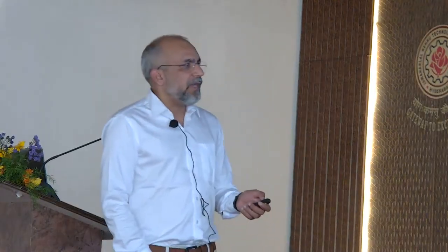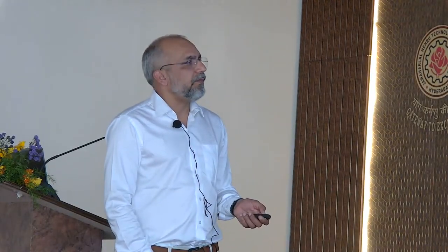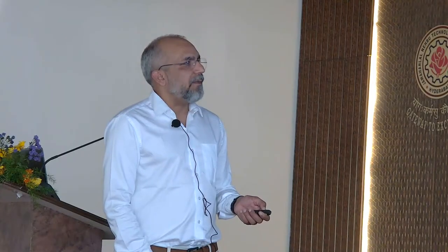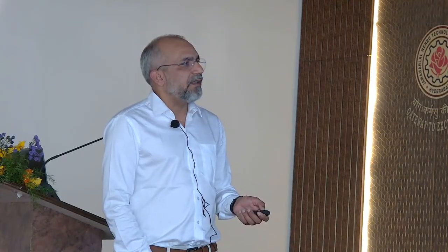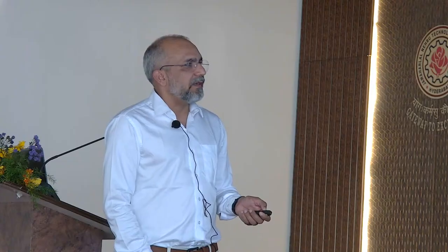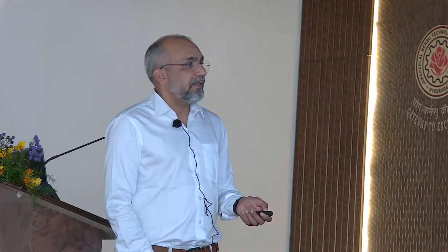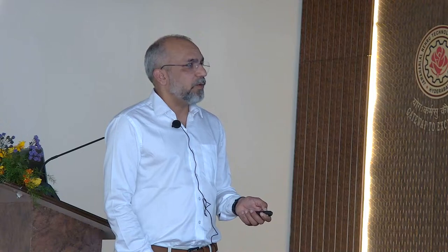Basically, we have a Mo container and a sulfur container. So we have these two containers here. First, sulfur will be evaporated, and then it will pass through the tube and interact with Mo and deposit on the substrate.